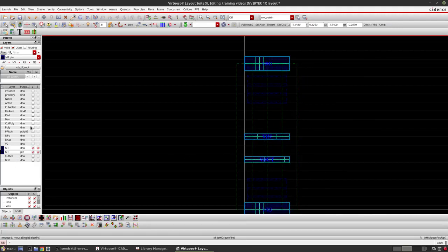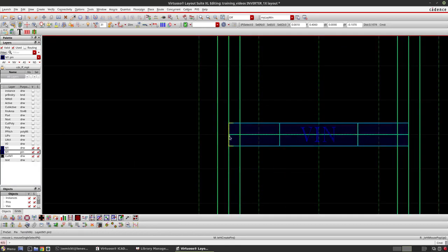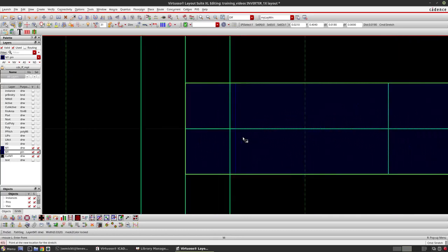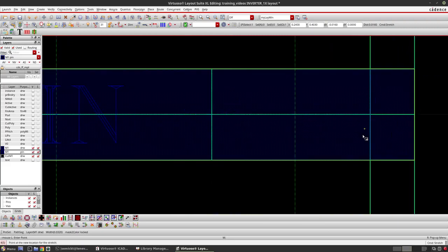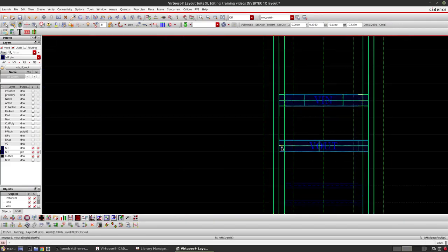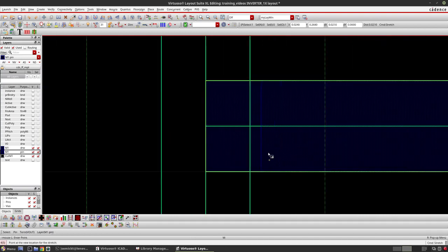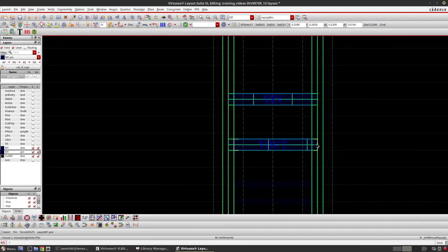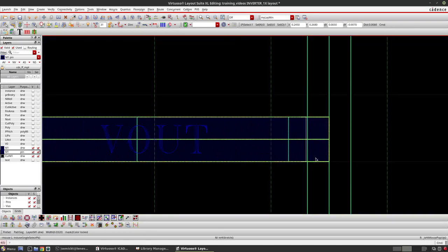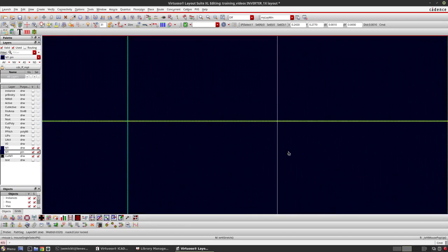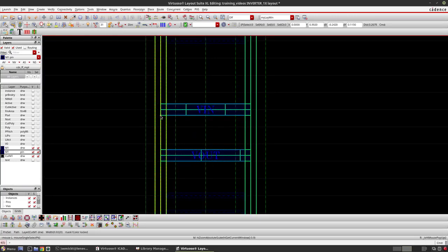One more thing that I need to mention is, you enable the cut poly. But this pin should extend from this cut poly. It should not be overlapping the pin metal.